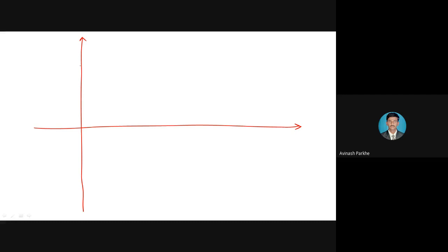Okay, so this is the vertical axis and the horizontal axis. This is plus sigma here, minus sigma. This is origin point O. This is plus tau, and at the bottom side this is minus tau. So accordingly, you also draw this particular vertical axis in your notebook. Make your notebook horizontal. Here again we have to select the scale. 1 centimeter is equal to 10 Newton per mm square. This is the scale we have selected to draw the Mohr circle.